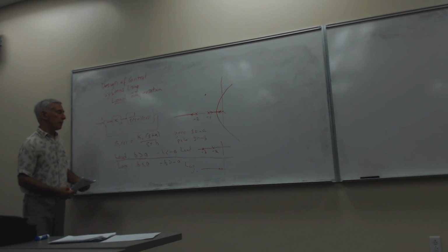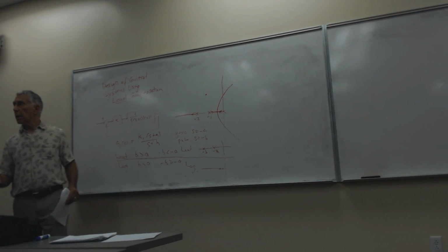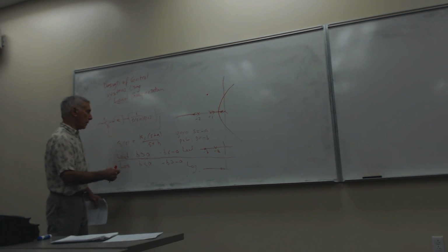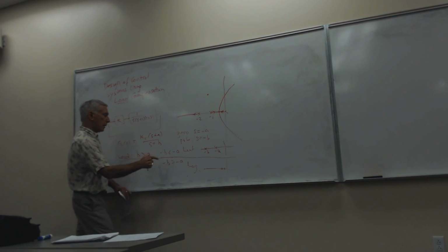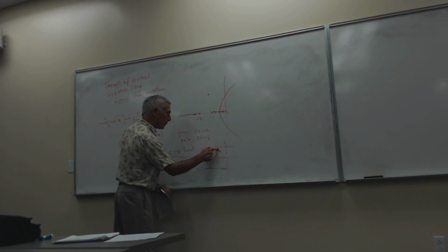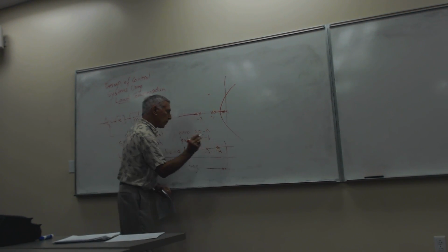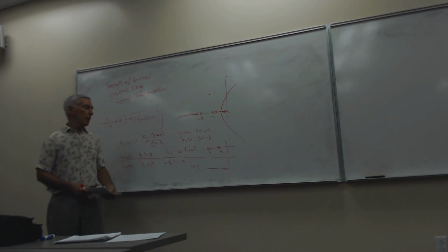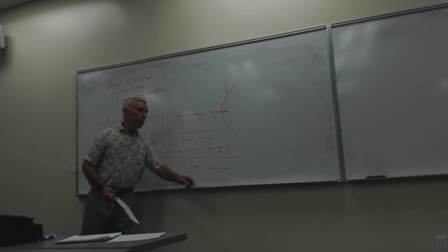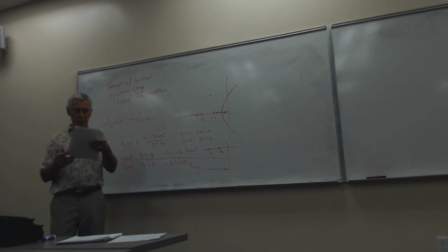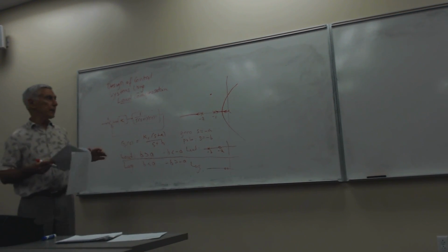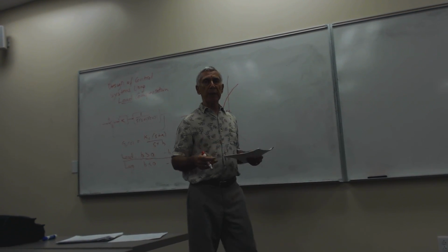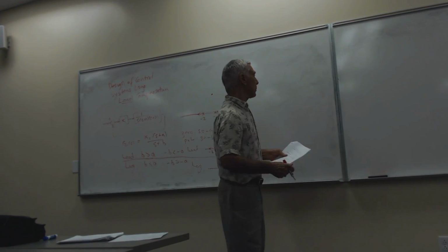Should A be a pole? They should be here, on the lead compensator, in the S plane. Oh, yeah, this is a zero. So the zero is to the right of the pole for the lead compensator, and it's just the opposite for the lag compensator.